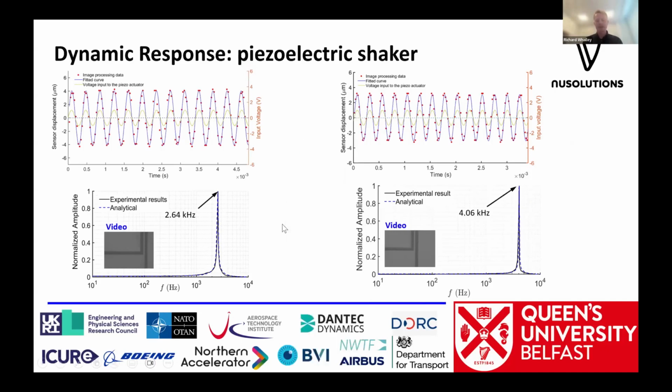And so what we do now is we take the sensor die, we place it on a piezoelectric shaker, and then we shake it back and forwards at a range of different frequencies. And so a couple of videos here that you should be able to see the sensor moving back and forwards, and you can just see that spring within that gap here.